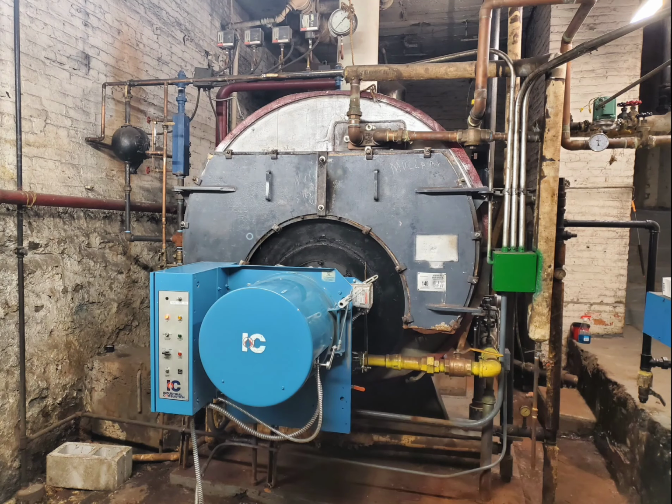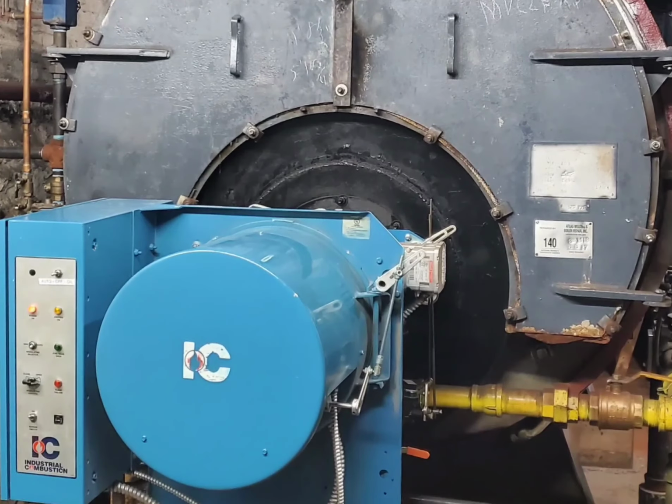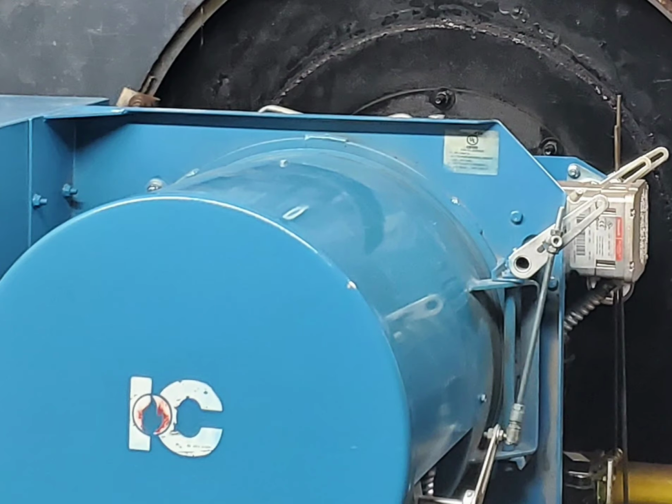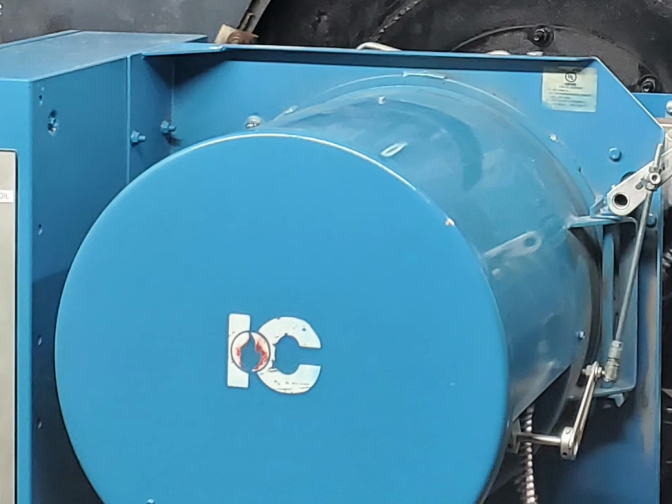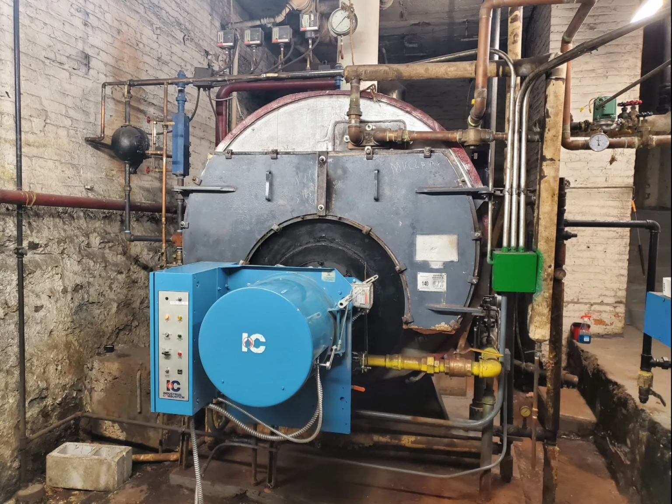Here we go. As a matter of fact, I could zoom in right here. This switch right here, this is a manual auto switch. Whenever I was making steam, I would put it on auto. And auto, pretty much what it did is the flame would reduce and the burner would just hold the steam pressure at 2 psi, 2.5 psi, wherever I had it set. So now with that being stated, let me go ahead and get back into his video.